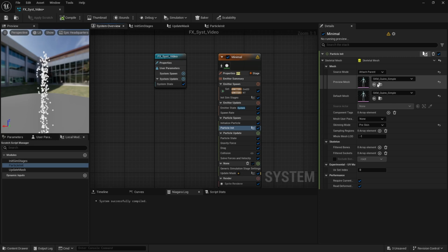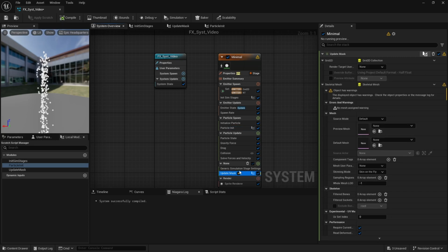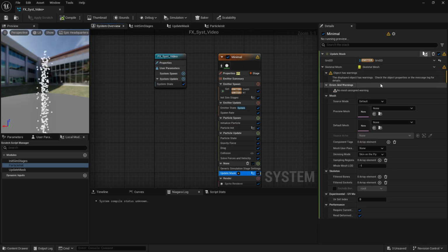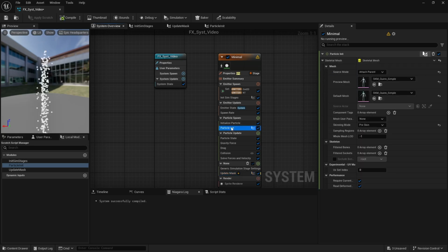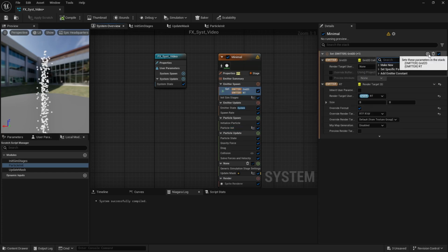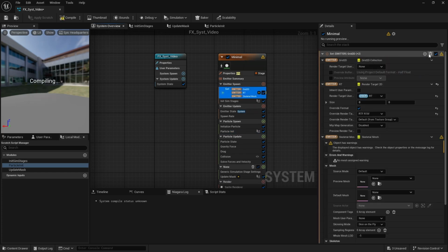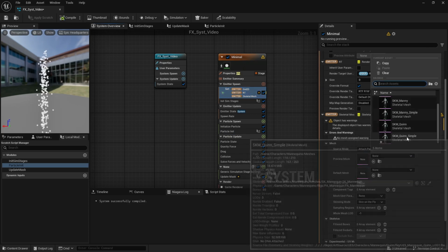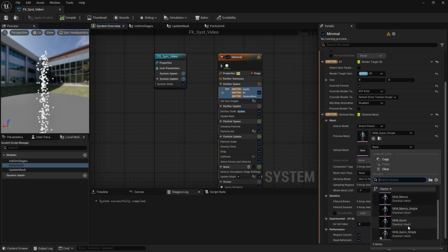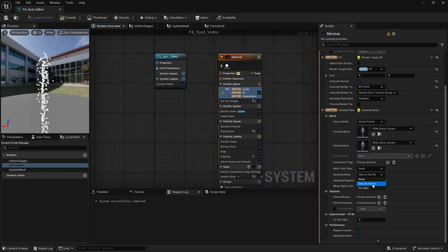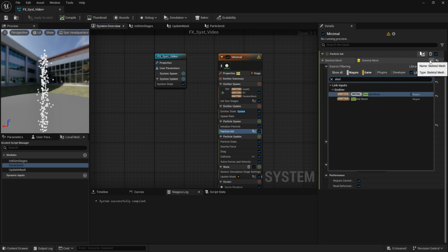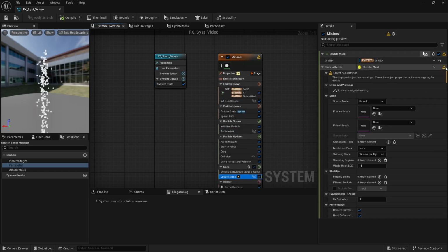Next, let's configure the module. The grid 2D input is the emitter grid 2D, and the skeletal mesh input could be configured the same way as before, but let's do something a little better. Let's create one at the emitter level and configure it just once. Attach parent, specify mesh, and use preskin. Next, set it here and here.